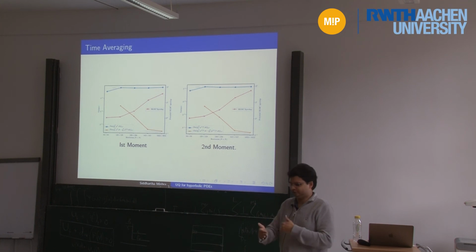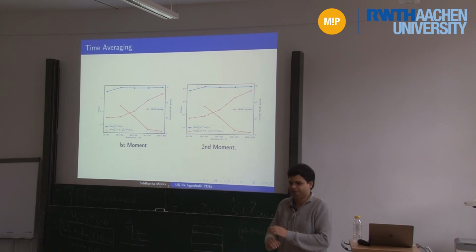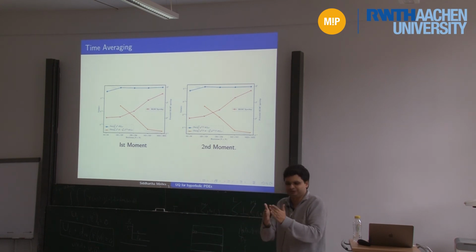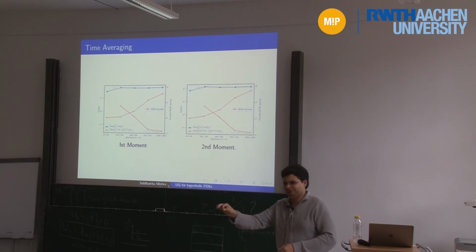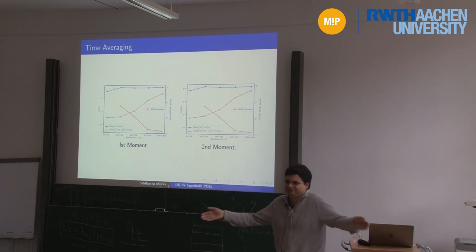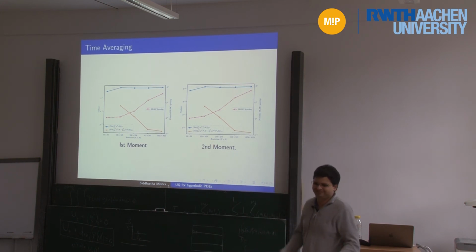Because we are always taking successive differences. It's not like we are taking a reference solution and comparing with the reference solution. Then that would explain that. No, we're taking successive differences. You get convergence, so the difference between 512 and 1024 is not much. So there are 2 factors for it. Either the solution has converged, or you have a very slow rate of convergence. You cannot distinguish between both. In either case you can't do any more. If it's a very slow rate of convergence, then you can't go to 10,000 cubed, right?